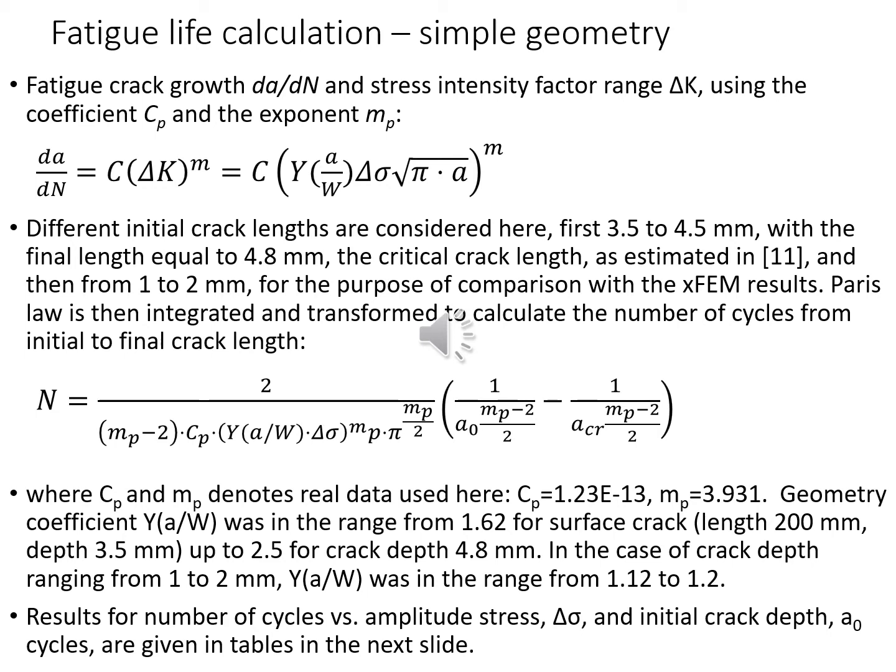So for the initial crack lengths which were considered here from 3.5 to 4.5, the final crack length was taken as 4.8. It was a critical crack length as estimated in some other paper. But then another two calculations were made for 1 and 2 millimeters for the purpose of comparison with the XFEM results.